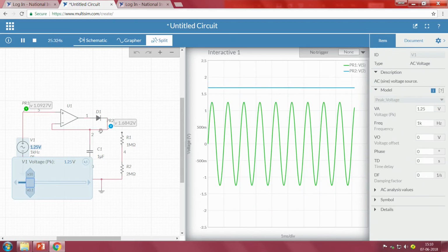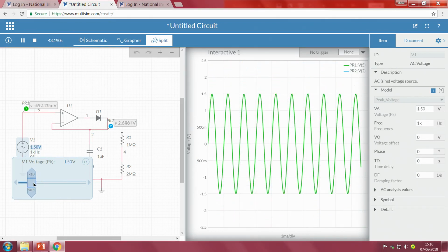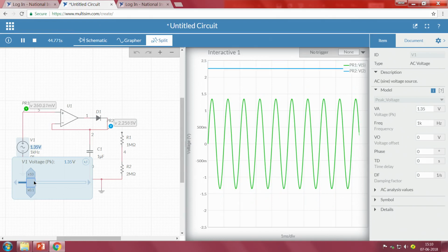Now, the capacitor started slowly decreasing, because the input voltage is now much smaller, and the capacitor will also take some time to discharge, because that entirely depends upon the discharging rate. So it started discharging, and again continuously maintains the value of the peak. That means one part is clear: whatever peak voltage we are getting, the capacitor will charge to that peak value.